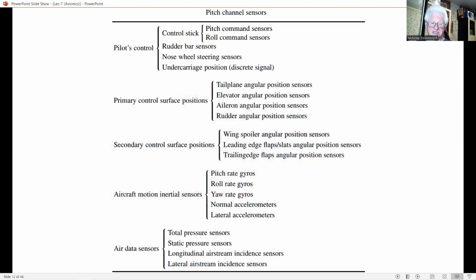Some appreciation of the functions carried out by the redundancy management software can be gained by considering the tasks involved in failure detection and isolation and reconfiguration in the event of a failure, in the case of a quadruplex system with 4 independent lanes of sensor and computer.